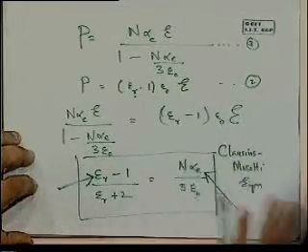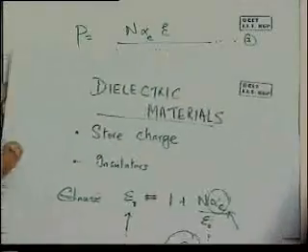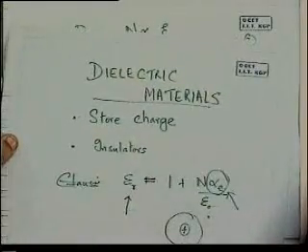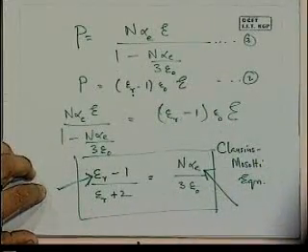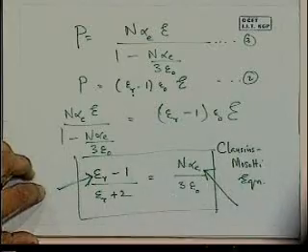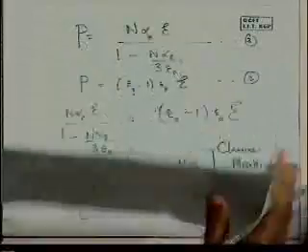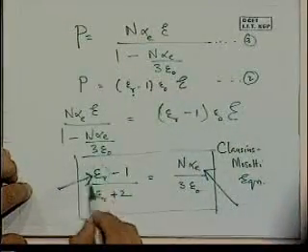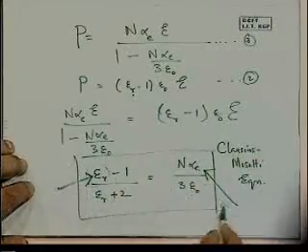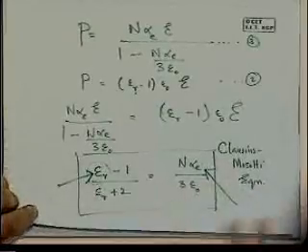So basically the difference between these two is that the first expression, where we did not account for a local field, underestimates the value of epsilon r. We will see that in a second: if you had the same information and used this equation to calculate epsilon r without considering the local field, or if you used the Clausius-Mossotti equation to calculate epsilon r, what would you get? And we'll see that Clausius-Mossotti gives you a higher value of the dielectric constant than the earlier approximation.